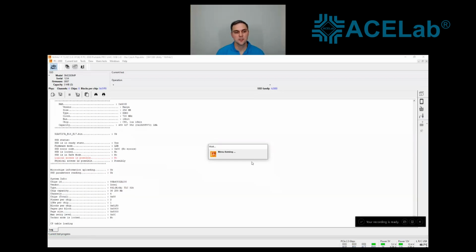And again, as always, we strongly recommend you launch the chip ID test to make sure that all chip IDs, all chip enables are fine and there is no problem regarding PCB bending or memory chip turning off due to high temperature and so on. So the contact between the PCB and the main chips must be very tight and very good.